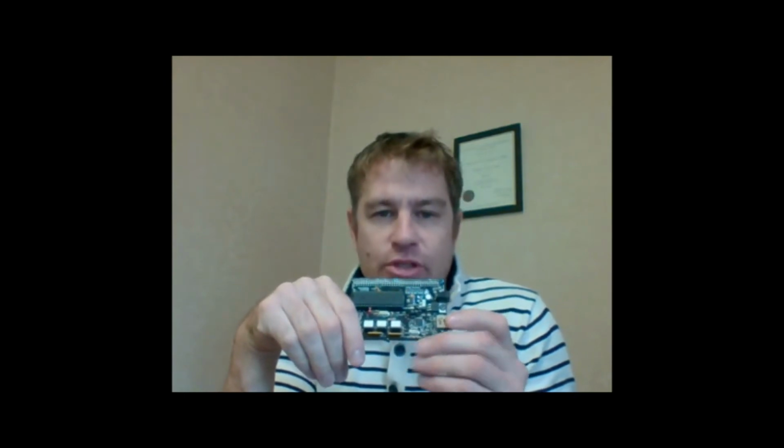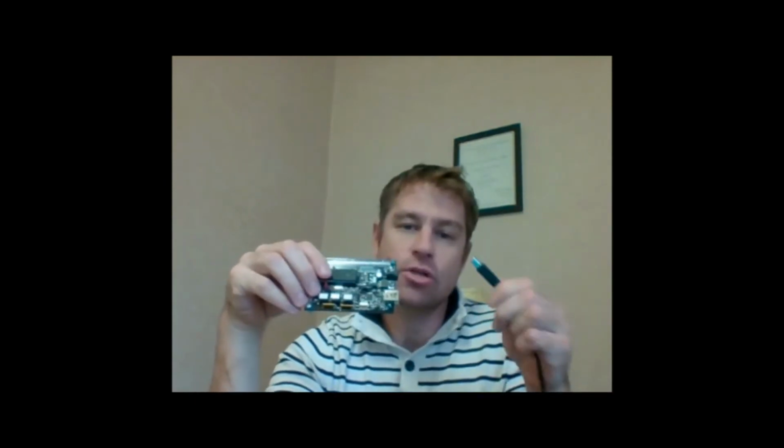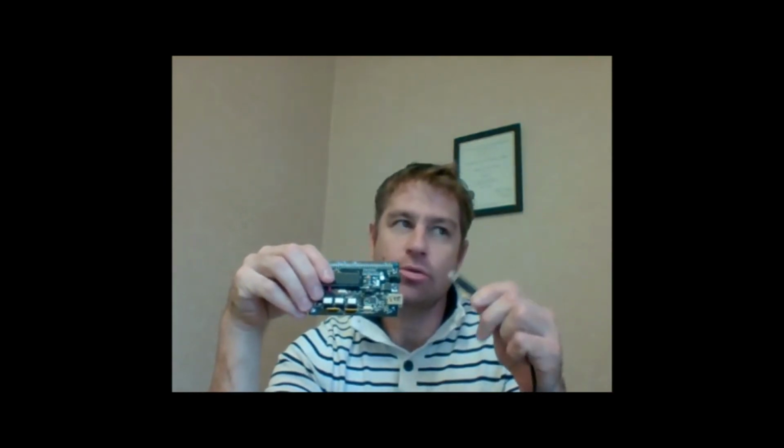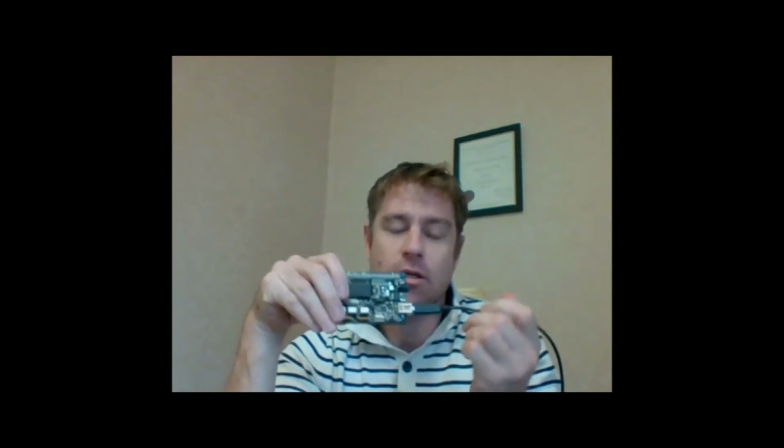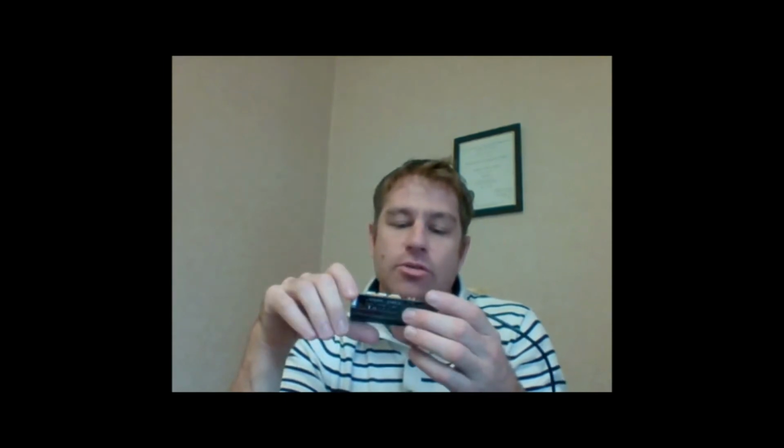Another important feature is the USB port. So this USB port allows you to connect to your computer, right? And we'll be able to not only download our programs, but we'll be able to communicate to our device using an RS-232 interface. To communicate to the embedded processor, there's an interface chip. So the little black chip that you see over here is an interface chip that allows you to do the communication. It simply converts and translates the different commands so that the embedded processor understands them.